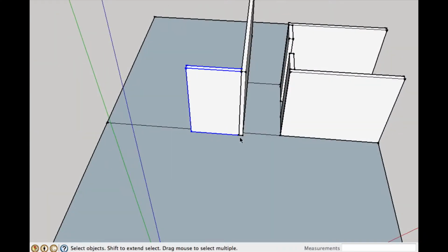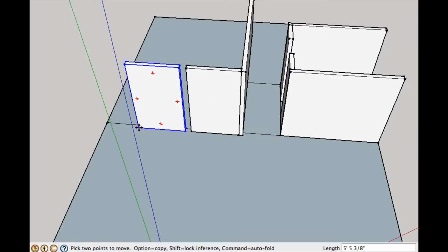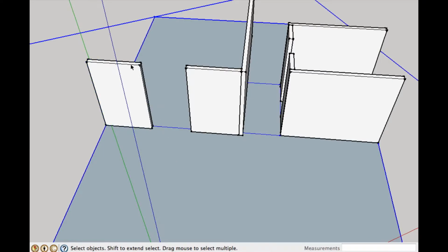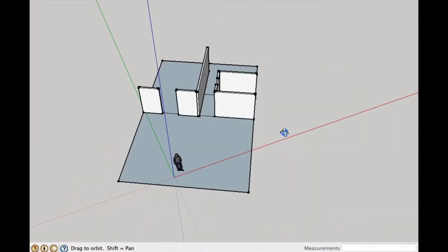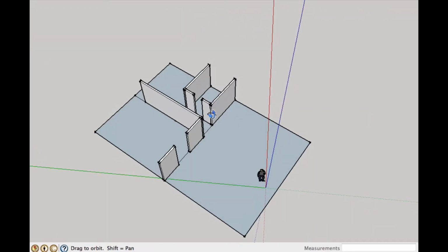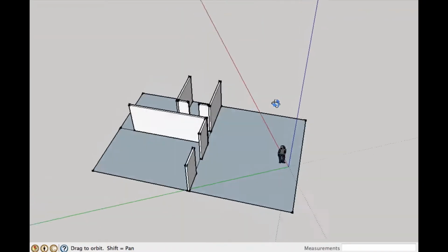And then we'll just copy this, holding down the Option key over, and to get it going, I'm going to work from there. Sort of pull from the corner that you want to anchor to a point. So if you know that you're going to this line, then copy from the edge, that corner that's closest to the place you're going to move to. So great, now I've got my interior walls of my house. And as you've seen, it's really easy to adjust those.